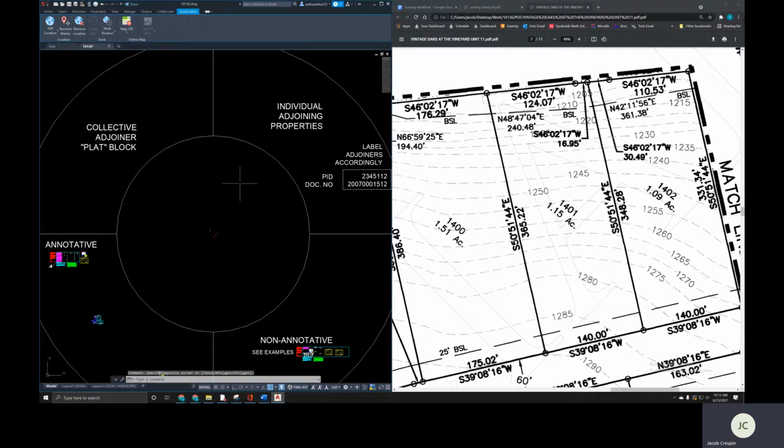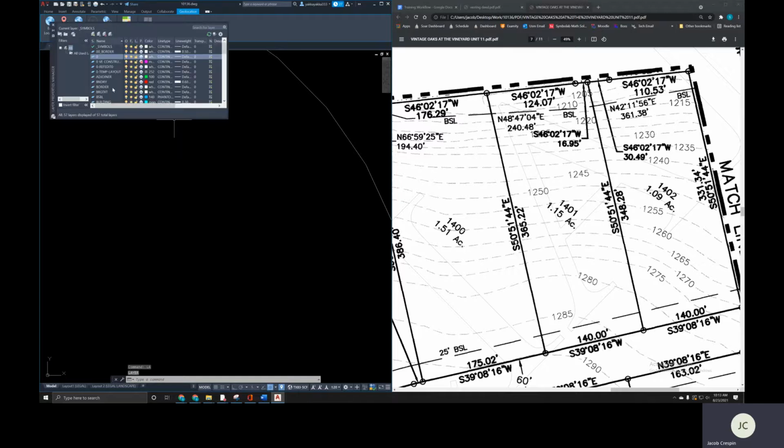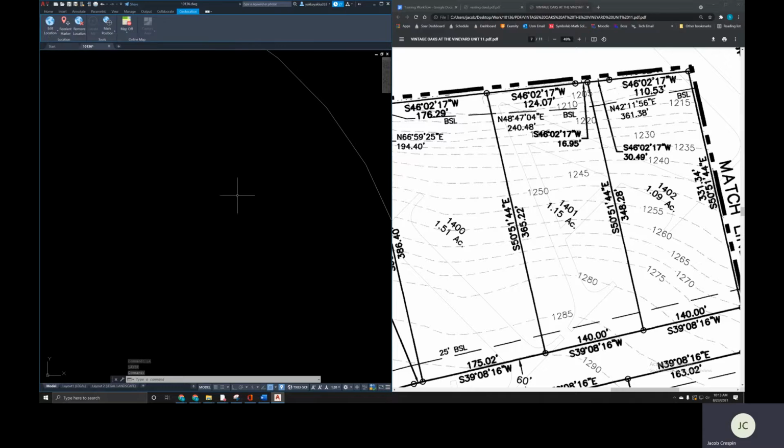We're going to copy the drawing that we've created and paste it here. Then we're going to block it here and copy that block and put it onto our property just to see where we are. So type LA to make sure we're drawing in the right layer. LA enter, and we're going to go to the boundary layer. Gotta click on the X at the top left, close it.